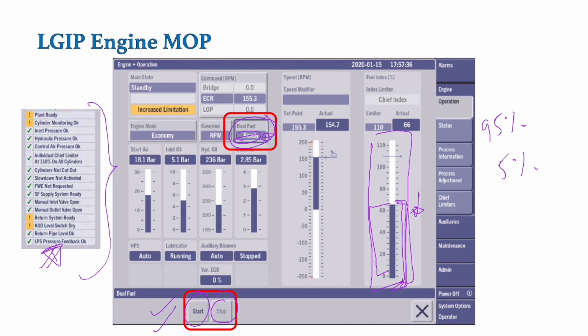So this is the condition that will come when the engine has fully changed over from primary fuel to secondary fuel. You must be thinking, why 95%, why not 100% secondary fuel? As I have already told, if you have understood the basics of a dual fuel engine, these engines basically cannot operate individually only on one fuel, that is the LPG.